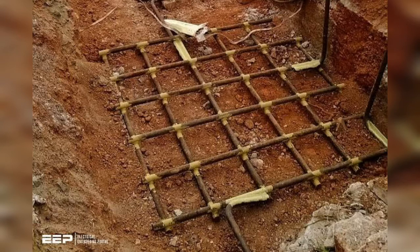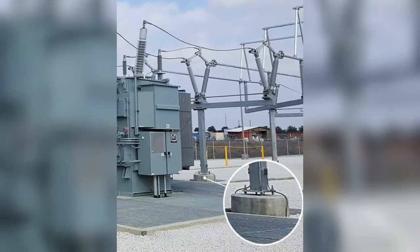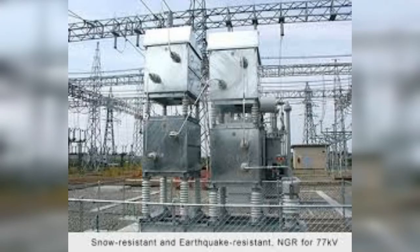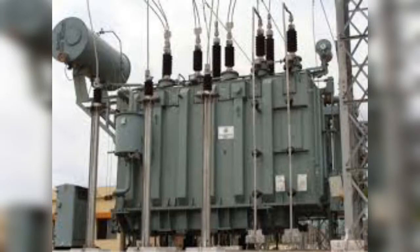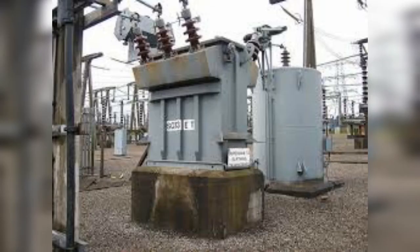We are discussing the grounding grids. The substation grounding system is an essential part of every electric system. The proper grounding of a substation is essential and very important for the following two reasons. First, it provides the main path for dispersing electric current into the earth without exceeding the operating limits of equipment. And second, it provides a safe environment to protect the personnel in the vicinity of a grounding facility from a danger of an electric shock under a fault condition.